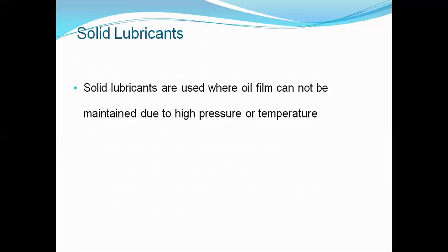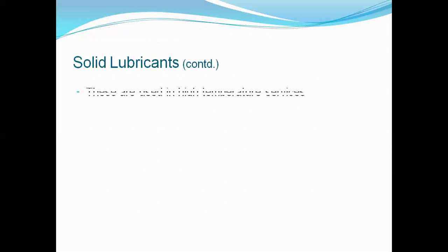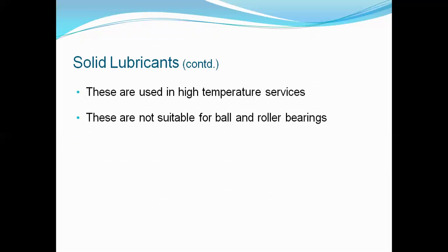Solid lubricants are used where an oil film cannot be maintained due to high pressure or temperature. Graphite is one of the best known solid lubricants. These are used in high temperature services. These are not suitable for ball and roller bearings.